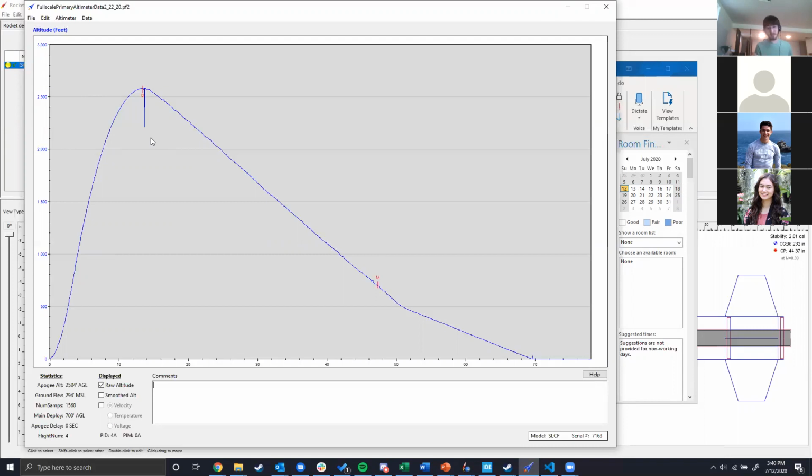It's possible that this might be due to a small leak causing some ejection gases to get in. Or sometimes you do just get jolts due to sudden accelerations. But the important thing is that these jolts aren't taking it all the way down to main deploy altitude, because that's where things go wrong.